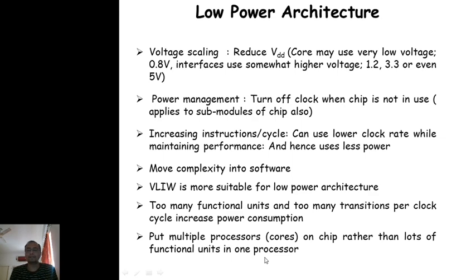Whenever all the cores are required to work, we can turn the clock of them on, and whenever we are not required to operate all of them in parallel, some of those units can be switched off, so power can be shaved. Such things are used in modern microprocessors, microcontrollers and DSP processors.